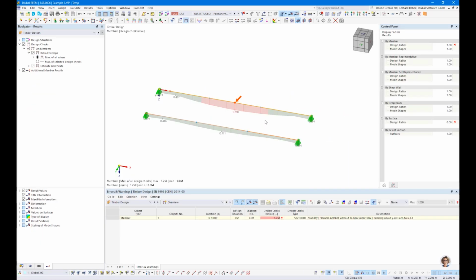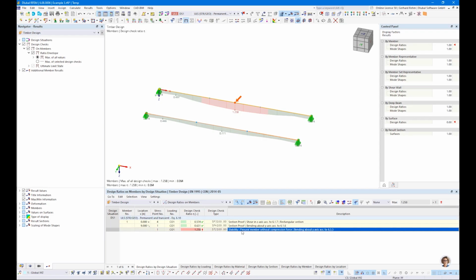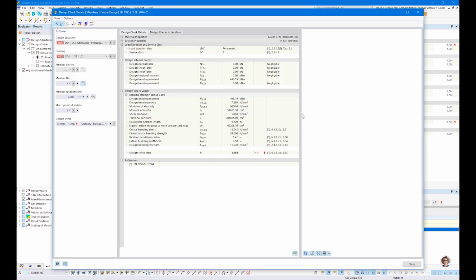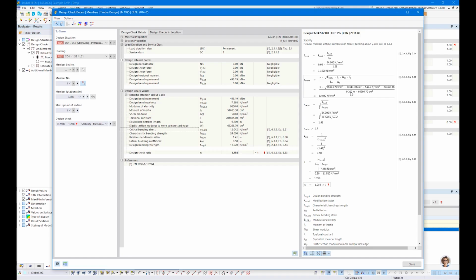Okay, and you will see that the eigenvalue solver shows us a result which is fine, but not the equivalent member design method by using this analytical equation. Yeah, this approach is too much on the safe side. We should use smaller buckling lengths in this case. So let's double check it. So we have 9 meter 20 in this case.